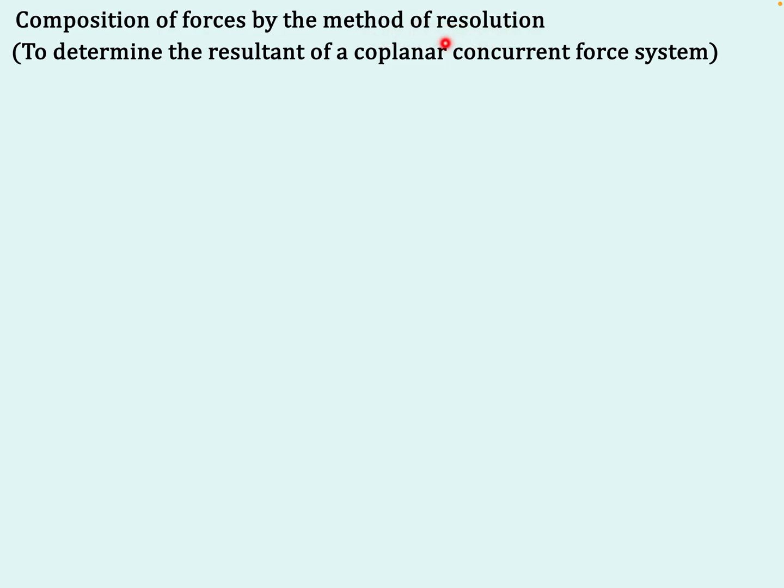Resolution is nothing but splitting a given force into its x and y components, or any other directions also. But we have seen that it is convenient to resolve a given force into its x and y components. So after having resolved this, how do we take it forward to find out the resultant of a coplanar concurrent force system? That is what we are going to see now.